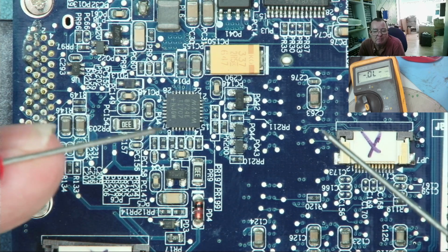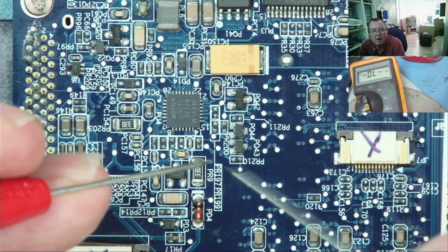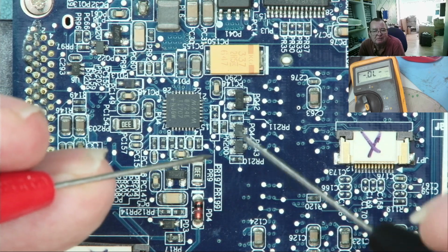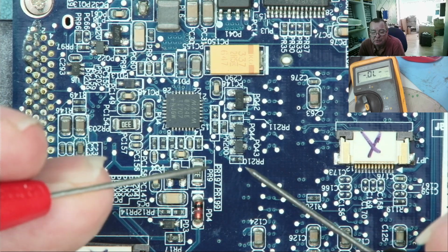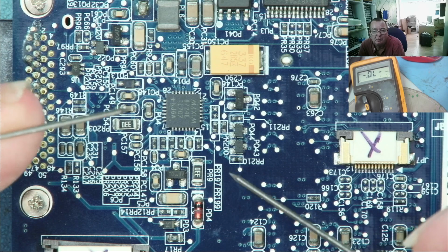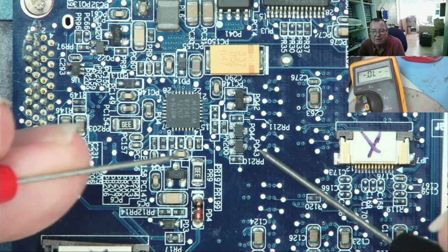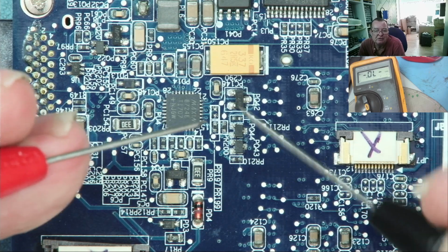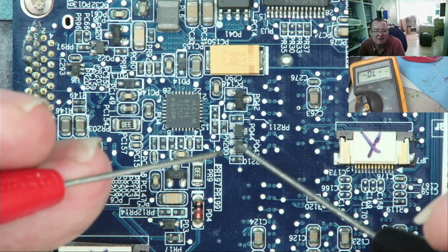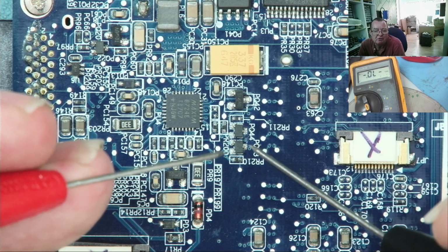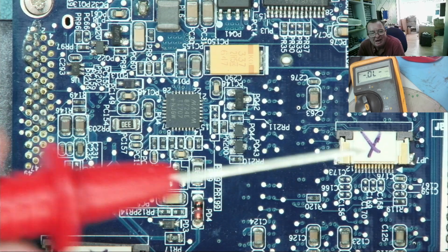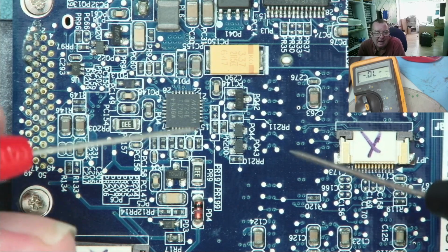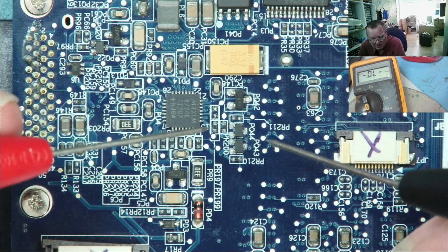And you'll find the same thing with bipolar transistors, where you found the base collector, base emitter, you can tell the voltage, one being slightly more than the other, which is emitter, which is base. But when you then go collector emitter, you find a diode. In that case, you know which is the base, you know which is the emitter, you know which is the collector, you know if it's NPN or PNP because of polarity of your lead. So you can say this is an NPN transistor or this is a PNP transistor.